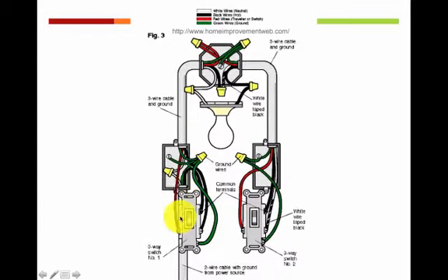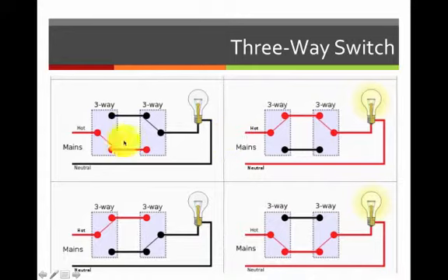So you have a neutral, and notice that it bypassed this white wire coming up into the box on the left, and notice that it will continue up. It goes into a wire nut, which is just a way of splicing together two different wires, and then it goes straight up and it connects to the light bulb immediately. So that's what we call the neutral connecting to the light. And if we look here, it's basically the same thing as a neutral, as labeled, connecting directly to a light.